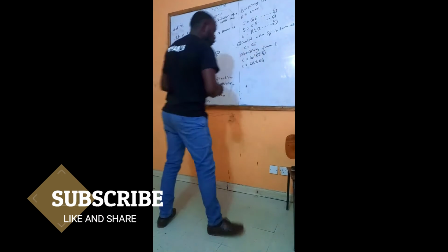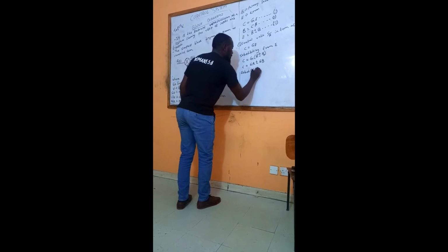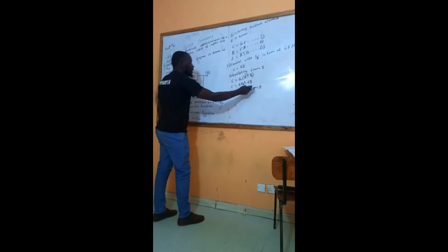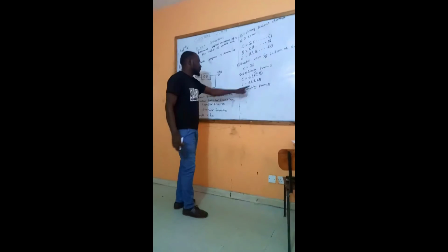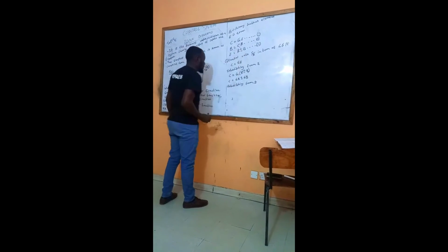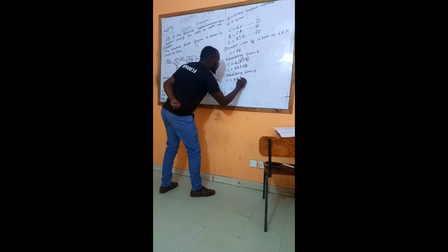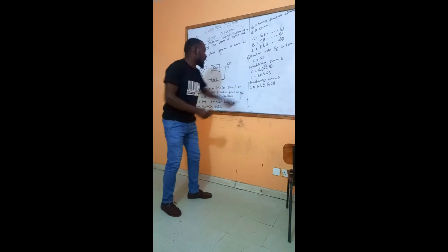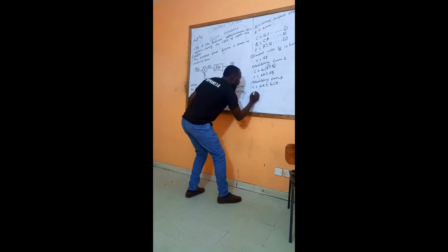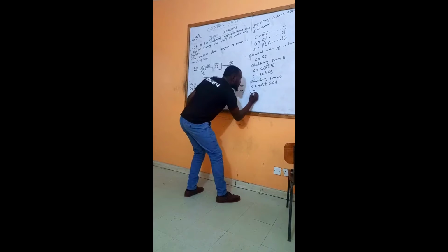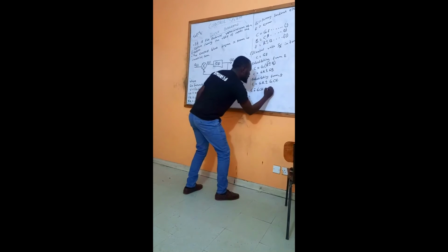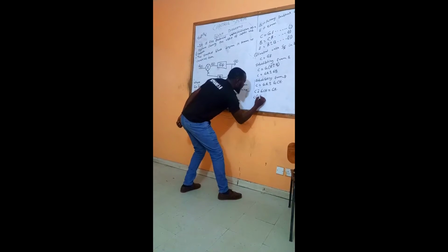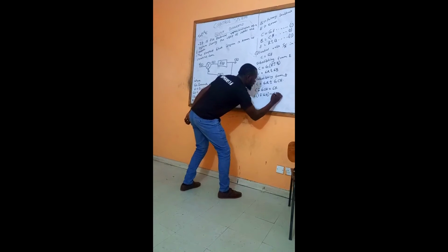After here, what you are going to do next is substitute again, this time for B. In our previous equation, whenever you see a B, you put in the value of B. Therefore, you have C is equal to GR plus or minus G times B. Our B is CH. From there, you collect the like terms. That means, what is here is C. This plus or minus moves to the other side, so we have C plus or minus GCH is equal to GR. Now, C, open the bracket: C times (1 plus or minus GH) is equal to GR.